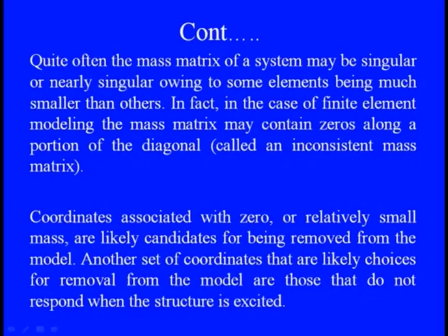The coordinates associated with 0 or relatively small masses are likely candidates for being removed from the model, and through that we can go towards the reduction of the model. Another set of coordinates that are likely choices for removal are those which are not responding actively when the system is excited. These are features that contribute neither to the natural frequency nor to the eigenvectors when the system is under excitation.